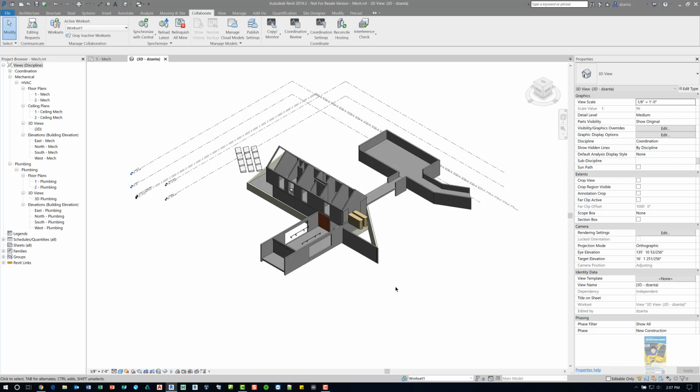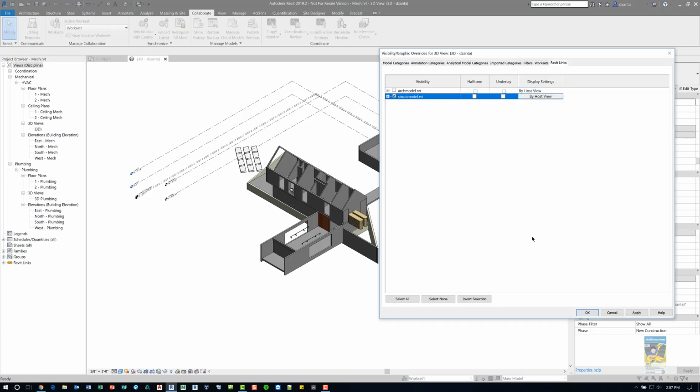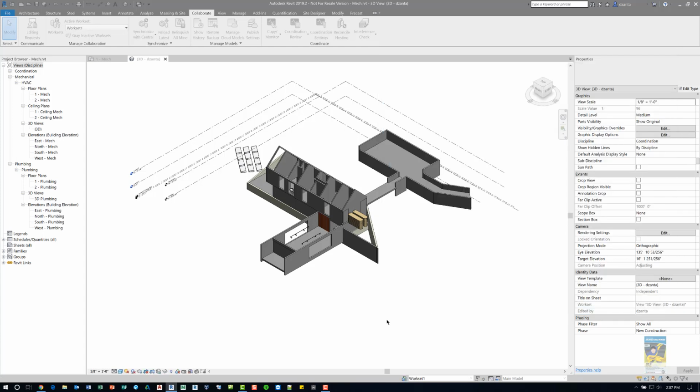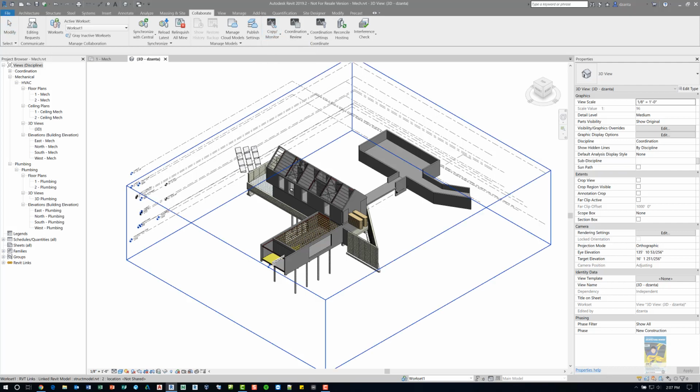Now, obviously, the copy command within Copy Monitor doesn't copy everything. It just copies a lot. And obviously, it just takes time for the software to evolve to be able to copy monitor additional content. So let's head over to the Revit links and let's turn the structural one on as well. And then we will do the Copy Monitor command again, where we're copying against the structural data.